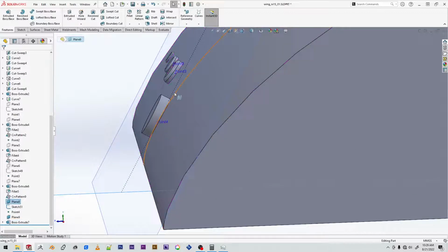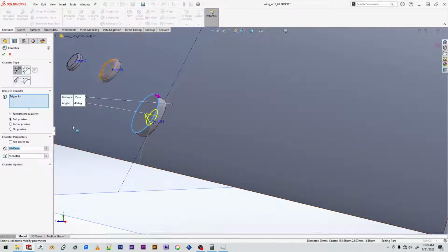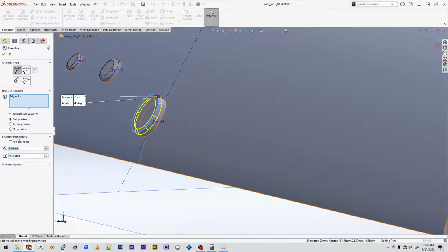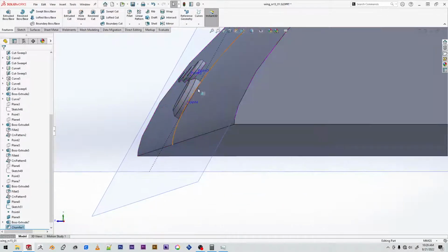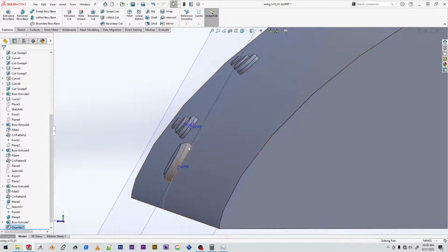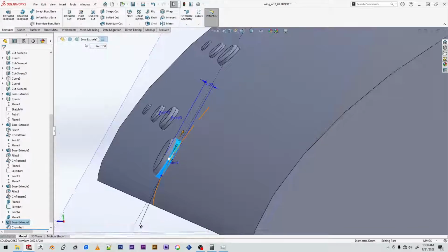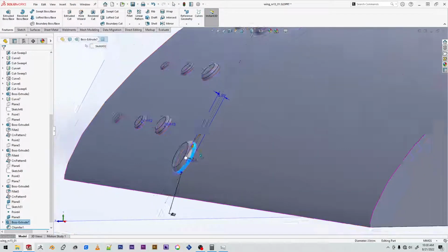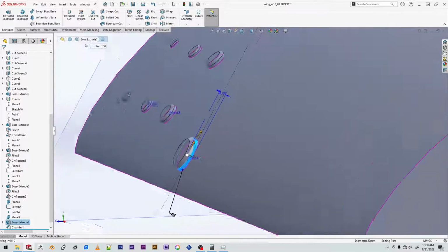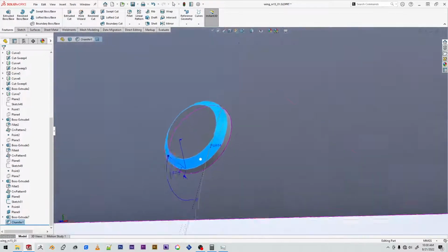So now you can see we've got this rivet, and let's just add a chamfer. These ones I added a fillet, but I'm just going to add a chamfer just to be different. So now we've got this rivet that's sitting flush. Now the rivet wouldn't be flush like this to the surface because rivets don't conform to the surface, but this is getting 3D printed and it's going to be a really small scale, so it doesn't need to be accurate. This is just for a model.